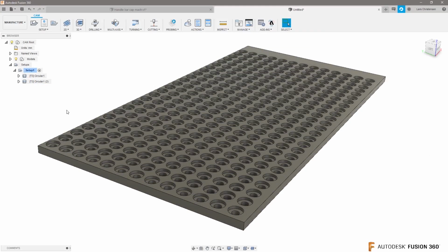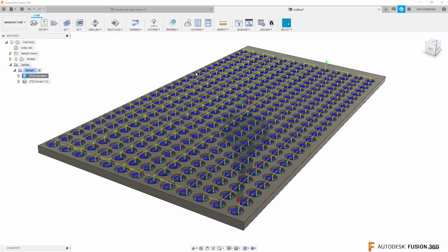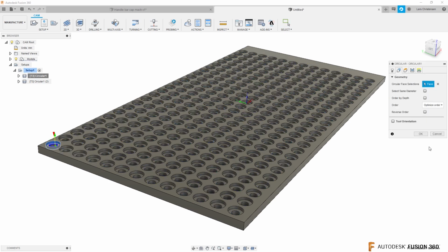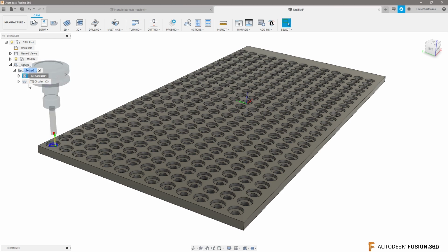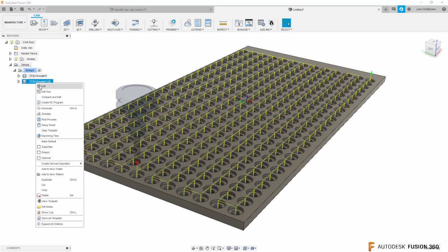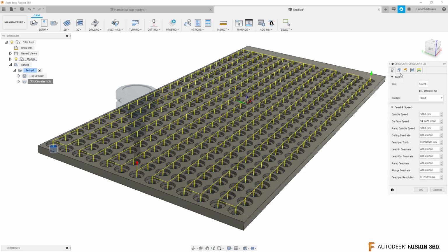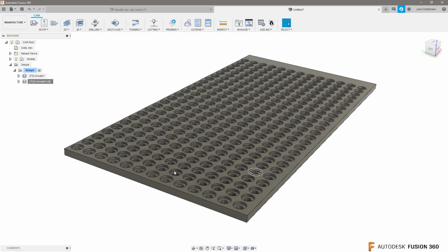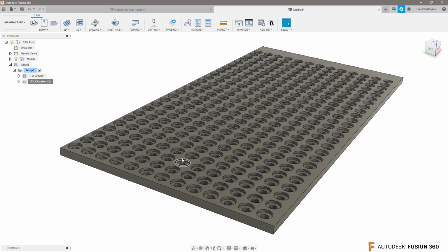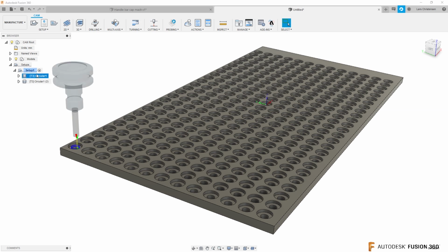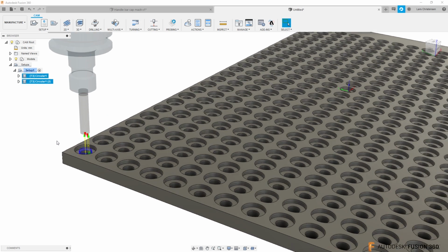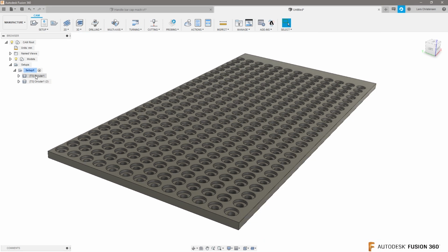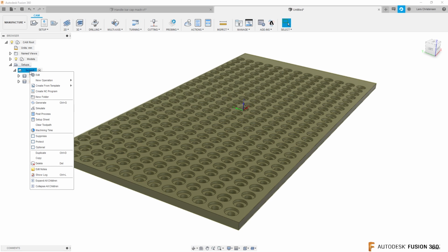The other way you could do this is, let's go back in and edit these toolpaths. Let's turn off the select same face, because what I think Gary maybe wants to do is actually machine one at a time. So I broke it down so I would machine all the top of the counterbores, then all the bottom of the counterbores. But of course, if you want to machine both of them in one, you can go ahead and do it. Inside of here, you can also do patterns.